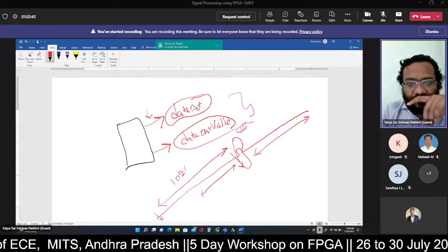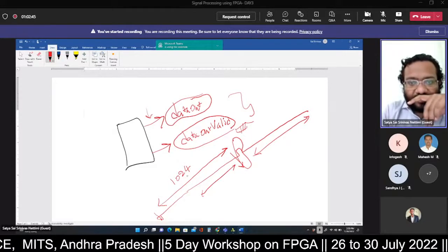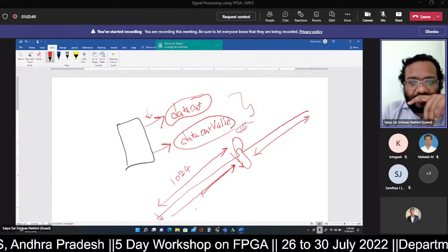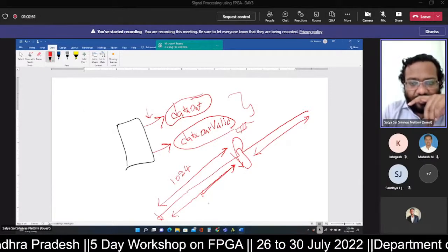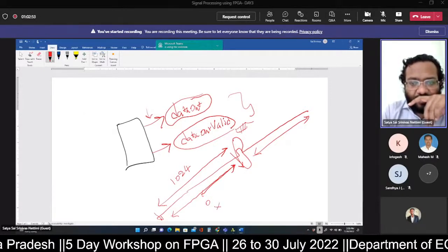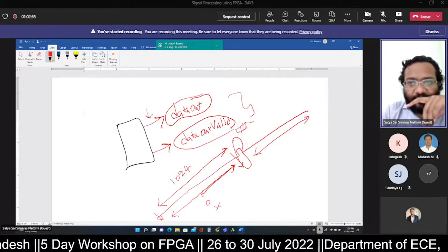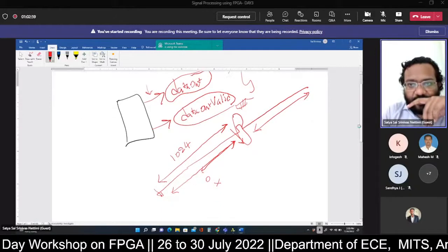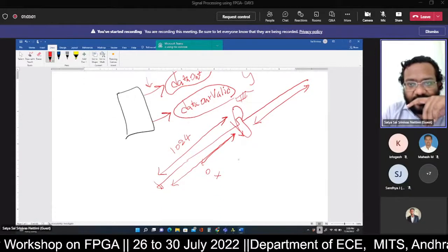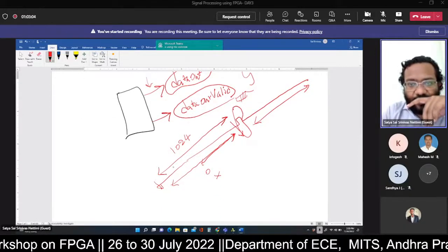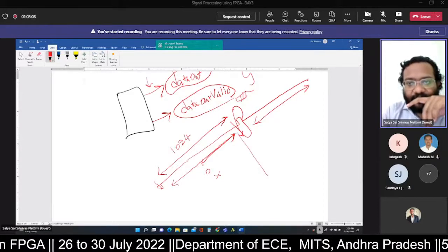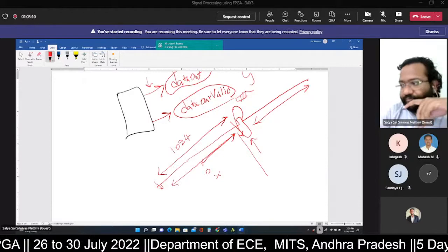In our ILA, we configure the memory depth to be 1024. From here to here, it is actually garbage data or no data, maybe 0 data or some unknown data. If you don't give a valid trigger setup properly, it will capture the data in the unwanted region, and you will not be able to observe the valid data.